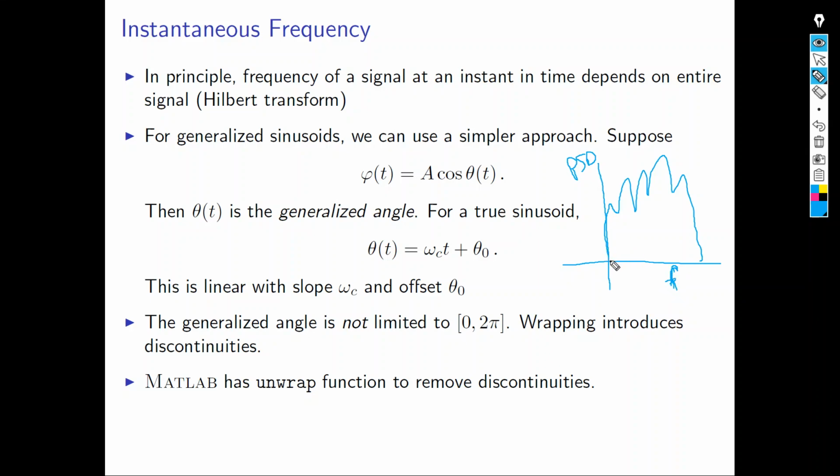If you want to find the power, of course, you calculate basically the area under this curve, the power spectral density. If this is power, and if it is time, this device also shows you the signal in time. You basically square this and integrate over the time to find the total energy of the signal. Now, what's interesting is that you can also see the behavior of your signal in time and frequency simultaneously.